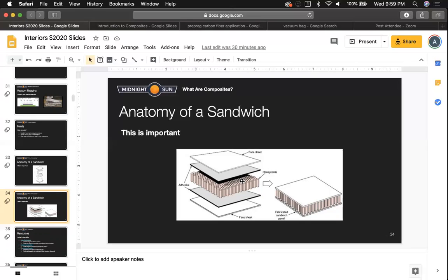If you're in mech or mechatronics, you'll learn about deflection and material properties. But essentially, the moment of inertia for any rectangular shape is proportional to the thickness to the third power, or cubed. That's proportional to the stiffness. So if you double the thickness of a panel, you're actually making it 8 times stiffer. You can check my math, but that's about the math you tend to use.